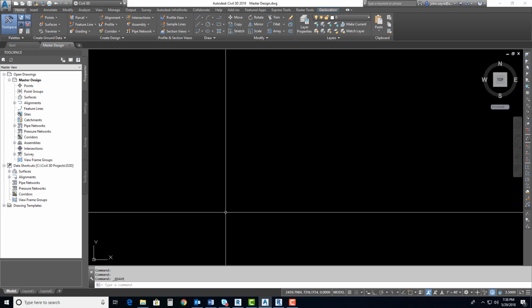You can just shut Infraworks down like I did, and it will release the model. Or you could go back to the home screen and open up another model, and it will release the model that you were in, and then you can open up the model here in Civil 3D and pull information across. Best way to do it is just to shut Infraworks down, and then you know everything's closed.